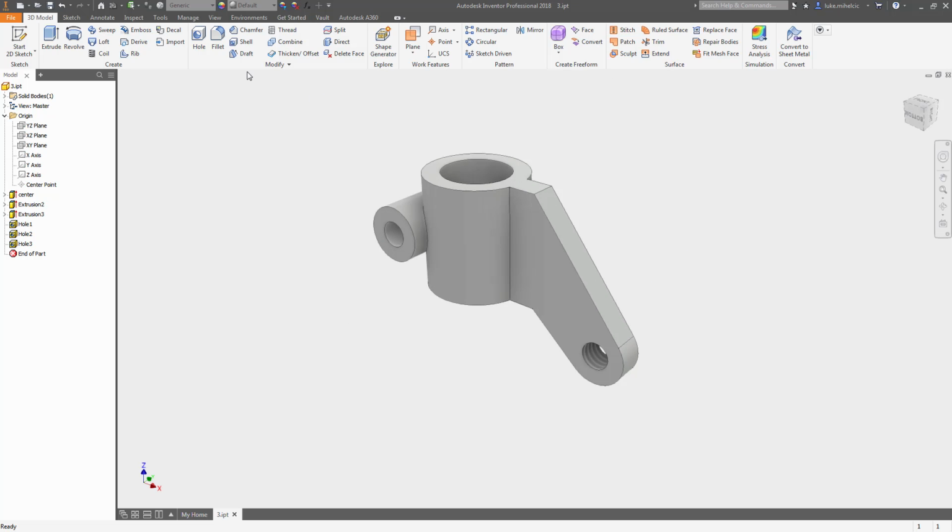So here's a tip for fillets. Again, if you can, do them at the end. The reason is, if you add your fillets during the process of creating your models, you may need that edge to dimension from or constrain to or to do something with, but if you've filleted that edge, you don't have it anymore. You might need to project some extra geometry or do some kind of workaround because you don't have an edge there. So I highly recommend, as much as possible, do your filleting at the end of your design.